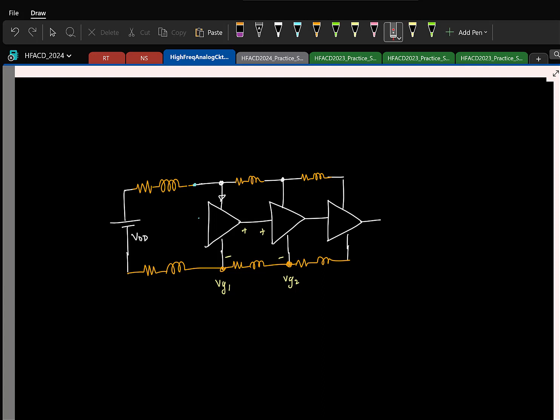So now if you think about why we have this problem, it's happening because the output here, let us say the output of the first block, is defined as a potential difference between two lines. The first line is local to this block, and the second line is the ground line, which is common to everyone, right? And since this ground line is common to everyone, everyone is dumping their garbage there and corrupting it, right? So if you were to be immune to this issue, what can you do?